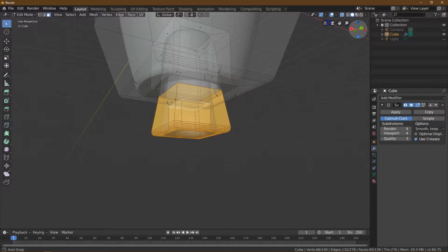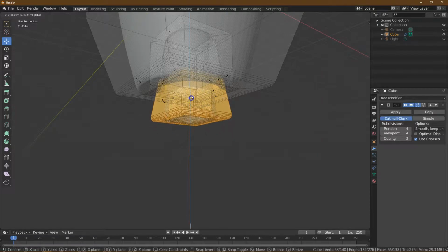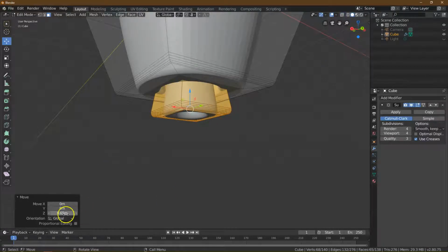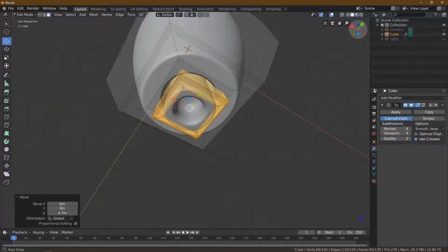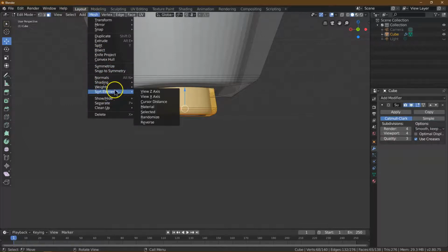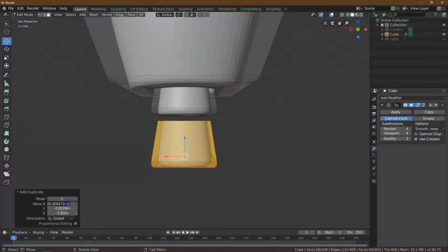We're going to push this all a bit down and duplicate it. So first, let me push it down 0.65. Let me take a look. 0.7 is looking good. So now what we need to do is mesh and duplicate. I'm just going to pull straight down. Okay. And so this should be 0 and 0 and -1.6 is fine for now.